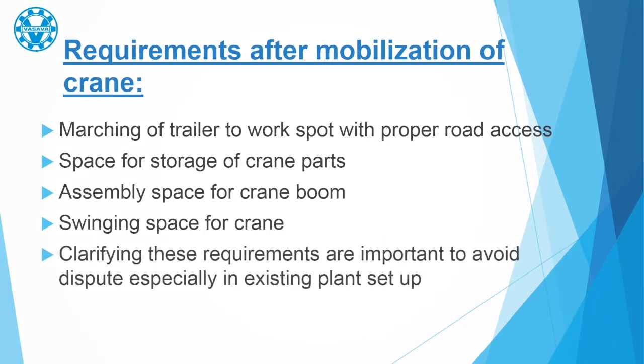Why are all these points discussed here? This is because at the 11th hour there should not be any controversy and dispute. This is a very crucial factor, especially in an existing plant setup. The requirement of one crane may be different from another. One crane owner may say that you have to dismantle a building because the counterweight will foul, whereas the other crane may not have that issue. Construction features of two different cranes are different.